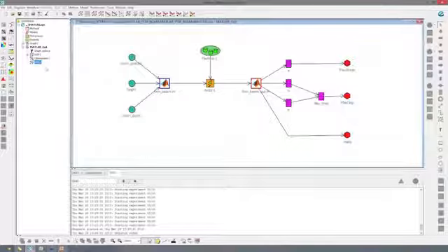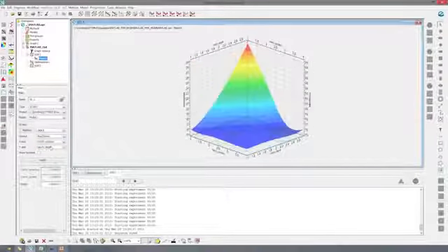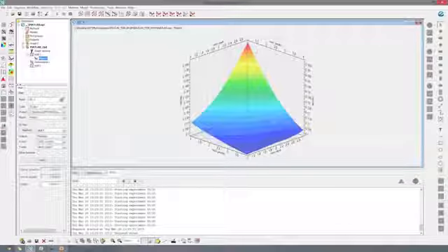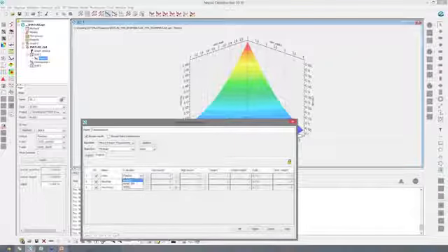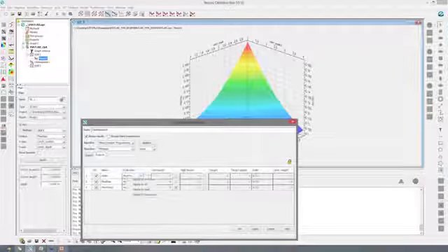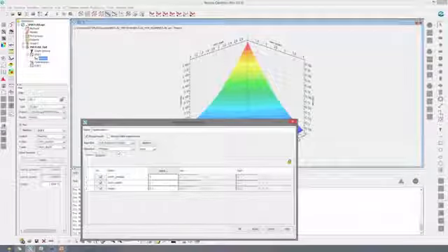Now the DOE is completed, and I've actually previously created a response surface on that design of experiments that you can see being shown here. And then I'm ready to run an optimization on that response surface. So we can select the response surface, and you see just with a few number of clicks, we select that we want to minimize the mass, and we select our self-adaptive evolution.